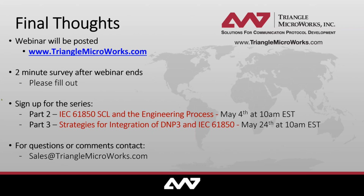We'll be talking a little bit about that during webinar 3, but you could also just simply do it in a gateway or protocol converter, such as our SCADA data gateway. And you would need an ICD file, an SCL file, which describes your 61850 device. But the answer is yes, absolutely. And you can do that in both directions, from DNP3 to 61850 or vice versa.